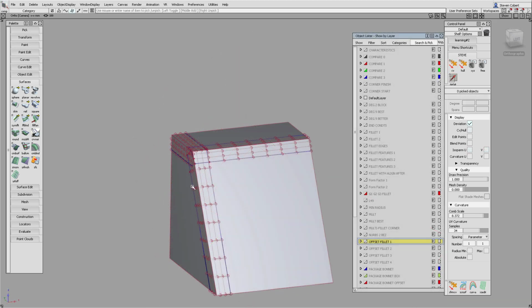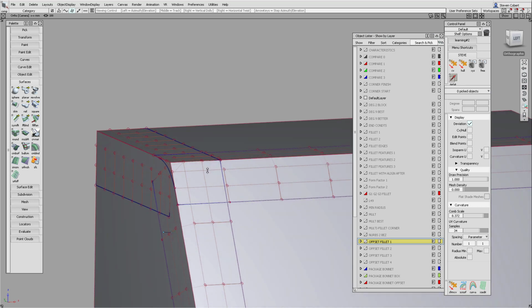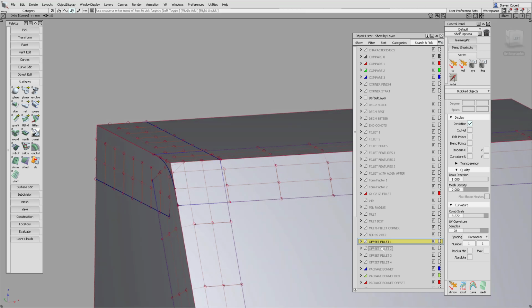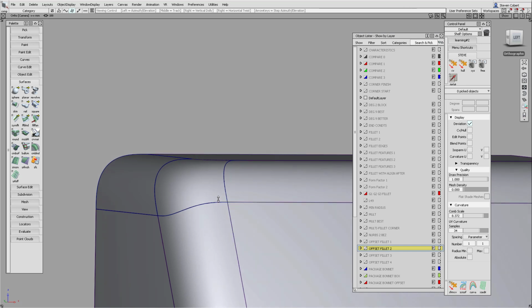In this situation, the block surfaces are at different angles. The fillets all have the same chord value. This means that the lower edges of the fillets are at different heights relative to the top surface. If the top fillets need to flow around the corner, then the bottom edge of the corner fillet will be S-shaped. To avoid this, we could use what I call an offset fillet.